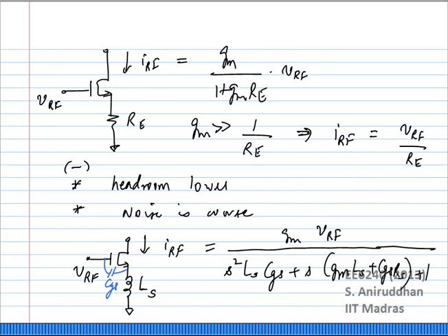over the region of resonance you will get very high impedance. At all other points you will get low impedance. The only thing you have to be careful about, the minute you put a capacitor at very high frequencies, the resonant circuit will be purely capacitive, so your input impedance will become negative. Okay, you don't want to start oscillating at the LNA output. That is the only drawback I see with that.